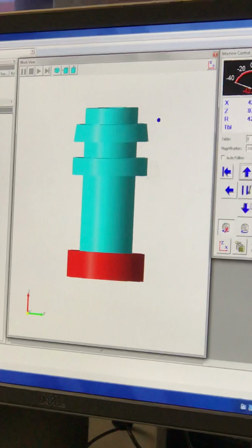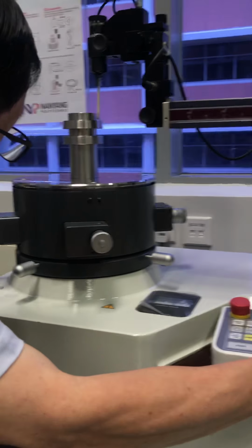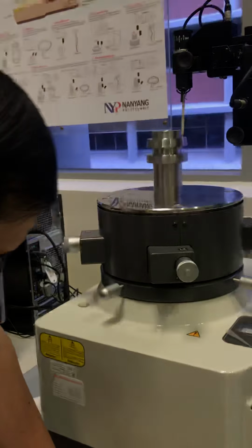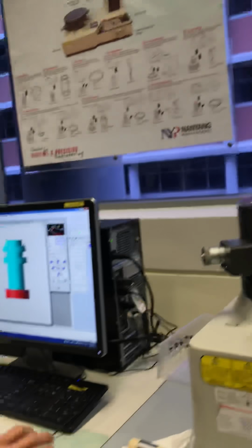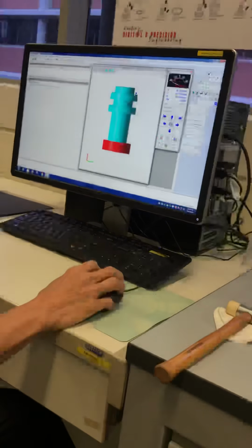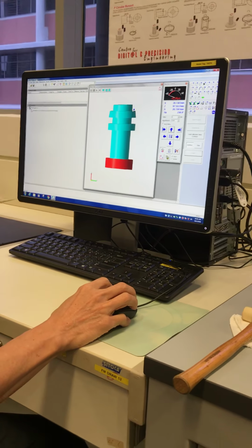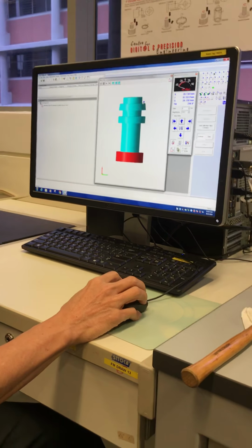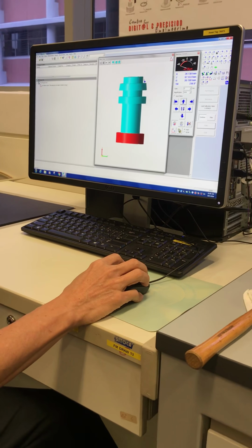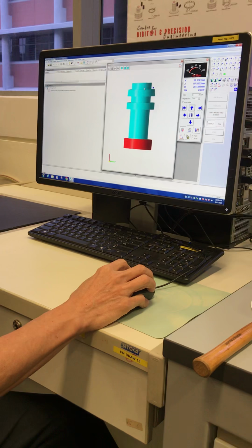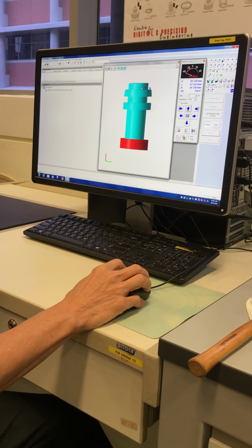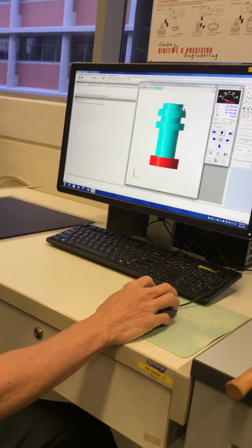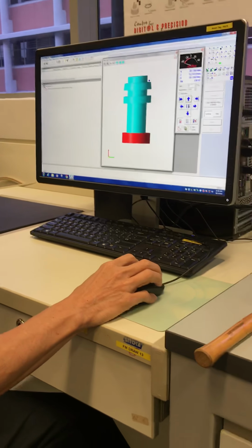Then you can bring this stylus up to the bottom here. Okay, so therefore you need to move manually here. Okay, we prepare the stylus here, and we are going to measure two circles. One circle slightly near to the bottom edge, and another one at the top, 6 mm away. So with these two circles, you can analyze the cylindricity. Clear? Any question?